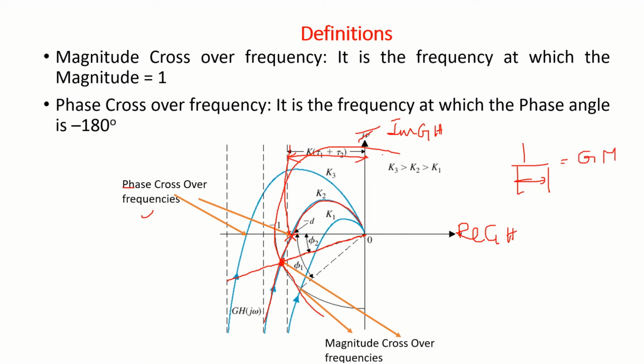It gives an idea. If you take this polar plot and complete the Nyquist plot, then the -1 plus j0 point is here. It is encircling, so it is an unstable case. This is a stable case. How far it is from becoming unstable is the question. So you take the reciprocal of this value, and we call it the gain margin.